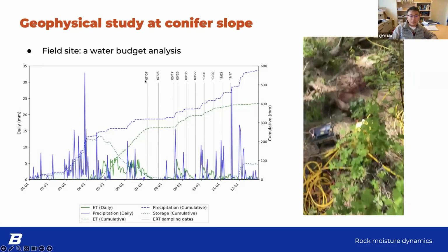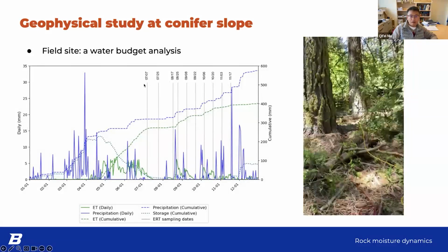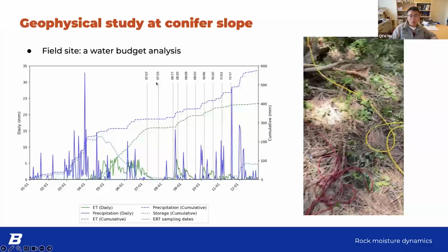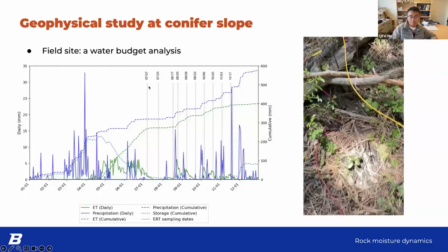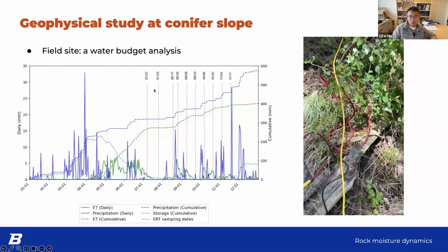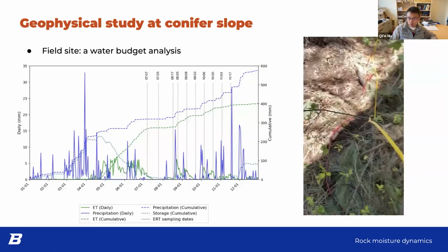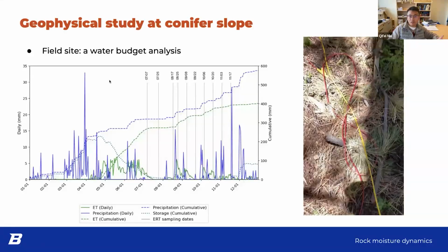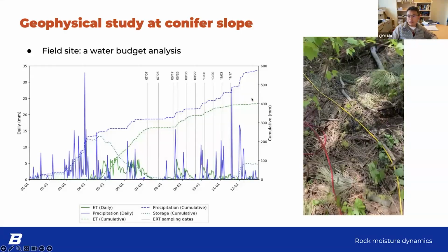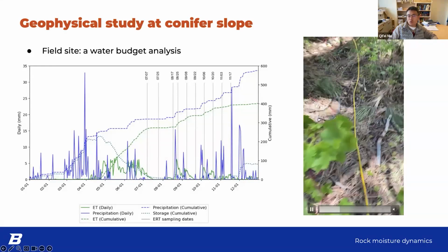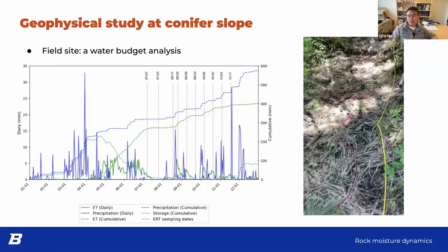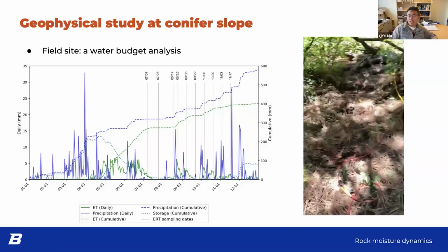And then we did about 10 geophysical tests roughly bi-weekly. We tried to use geophysical electrical resistivity to see how the subsurface storage changes over time after this big snowfall. So you can see the site is not easy for running the resistivity test. Even walking is not easy at all.